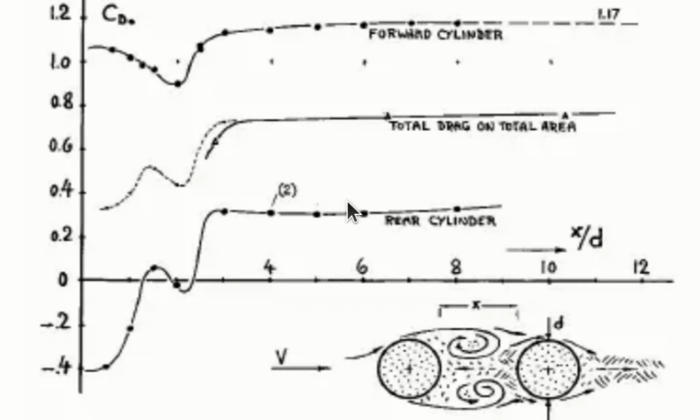So that means that on an ultralight, where one round tube strut is in front of another, down near the fuselage, you actually have reduced drag in that area. So that's kind of neat. That means it's fairly beneficial to use your round tube struts. Now we're not actually going to compare round tube directly to teardrop shaped tube, because I imagine that the teardrop shaped tube would actually be better. But you're not paying a huge penalty down near the fuselage where you're using these round tube struts.